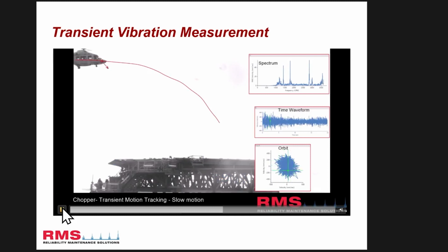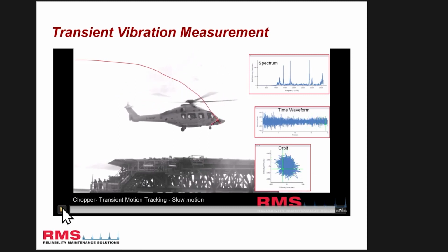This is me playing around offshore, seeing if I could measure the vibration on the chopper as it landed. It just proves that we can still take spectrum for frequencies, time waveforms and orbit plots relevant to an ROI on a chopper that's moving. This is a bit gimmicky, by the way, just for presentation purposes, but I was playing around and got a bit bored, really. So I just thought if we could do that, it's pretty good.